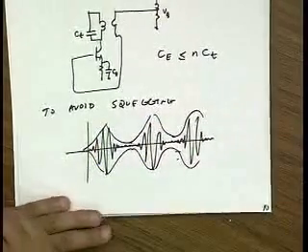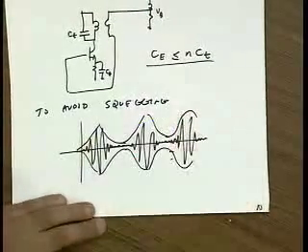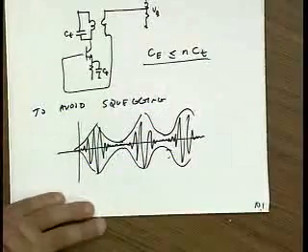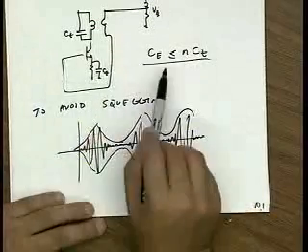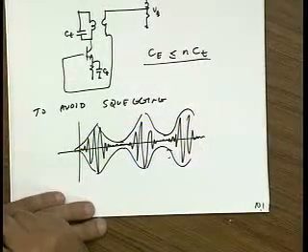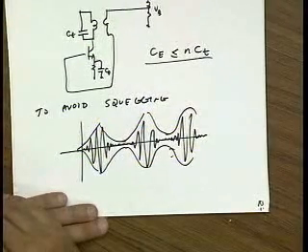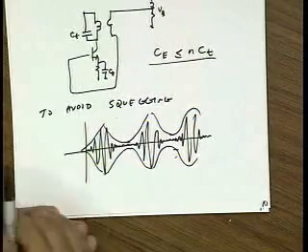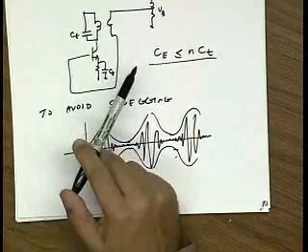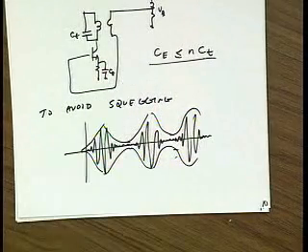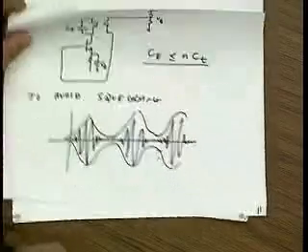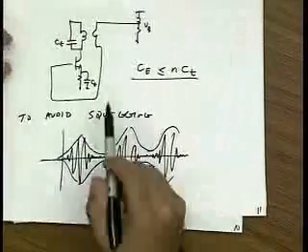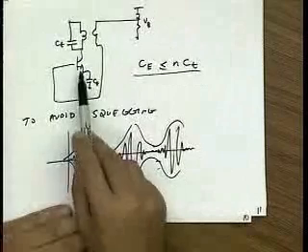Okay? Now it's fairly complicated, and I actually don't know how to derive this equation. I should think about it. But somebody's derived this relationship and tells you for this particular oscillator, keep CE less than N times CT, and the circuit works. Al, do you know how to derive this? Yeah. Okay. Yeah, it's definitely the RC time constant with the gm of the transistor, yeah.